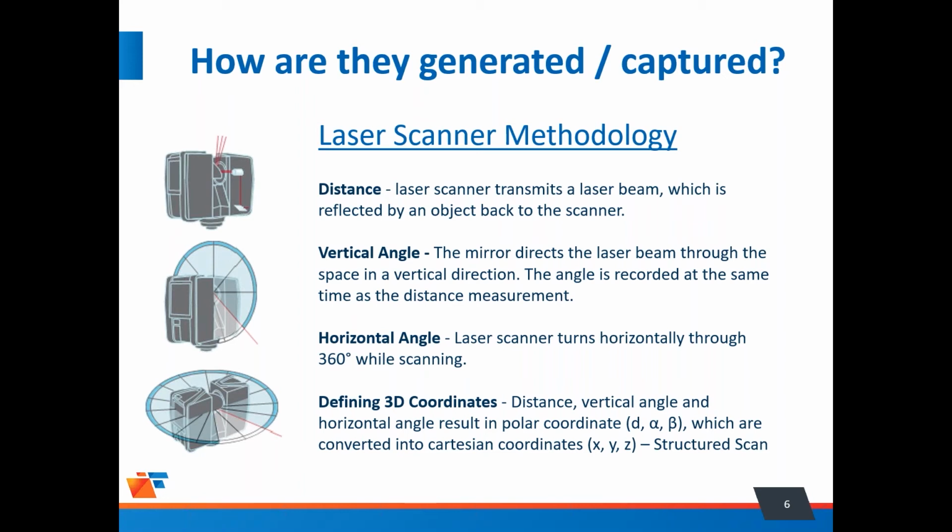They are line of sight, so they don't see through walls. So if you need to capture something that has a lot of little rooms, then you're going to have to take a lot more scans. Depending on the complexity of the project, you may have hundreds or thousands of scans, and it may take several minutes per scan, depending on which method or which technology you use.